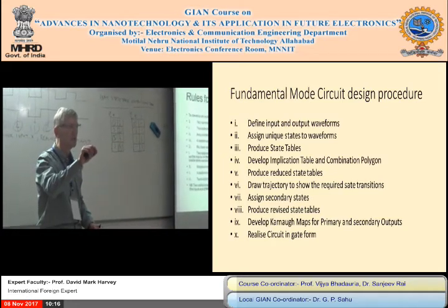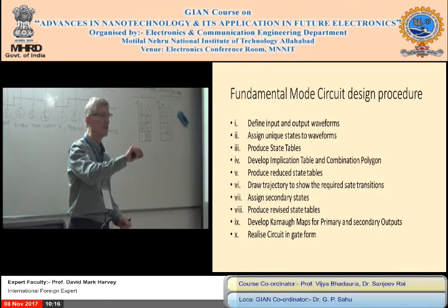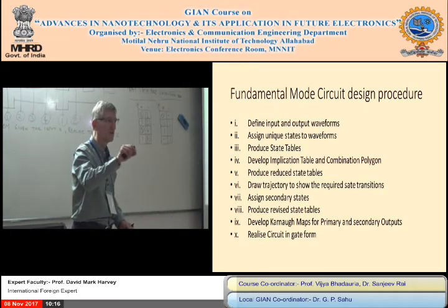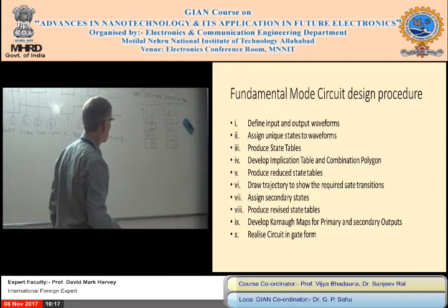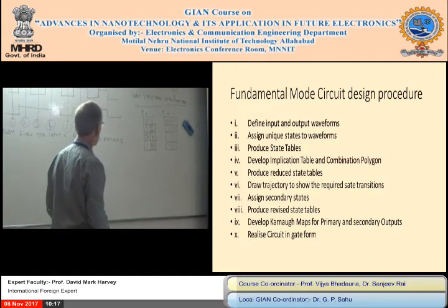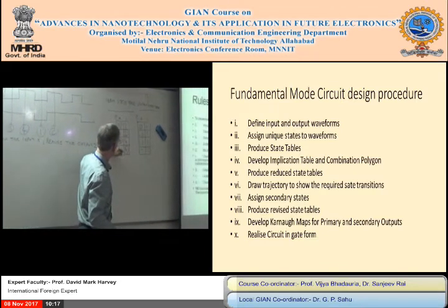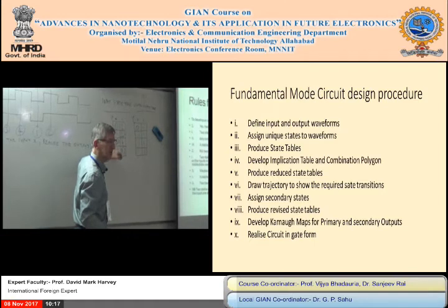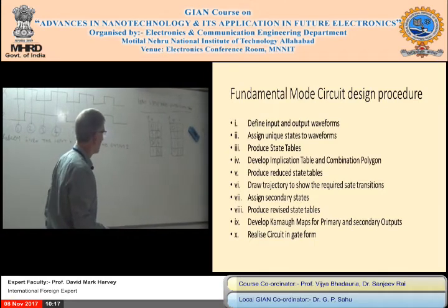In our implication table, we can't make a decision on that until we look at if stable state 2 and 4 can be combined in a different box. 2 transition states of different numbers. Again, in this column we've got state 1 and state 3, transition states. That's only implied. You only make the decision on the stable states.